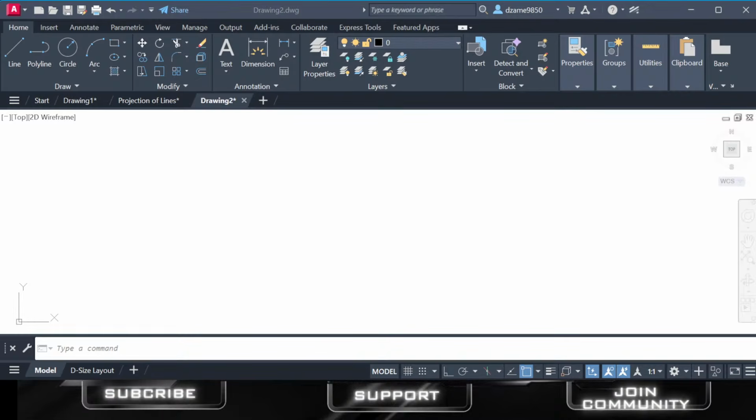And below here is what we call ribbons. What are ribbons? For example, the Home ribbon is active. So you go in between by clicking all these ribbons. This is where most of the tools are located. For example, in the Home ribbon, you can see several things like line, polyline, circle, and so on. All these are under the same ribbon. You notice that they are grouped into tabs, and these are specific tabs, like Home, Insert, Annotate, Parametric.